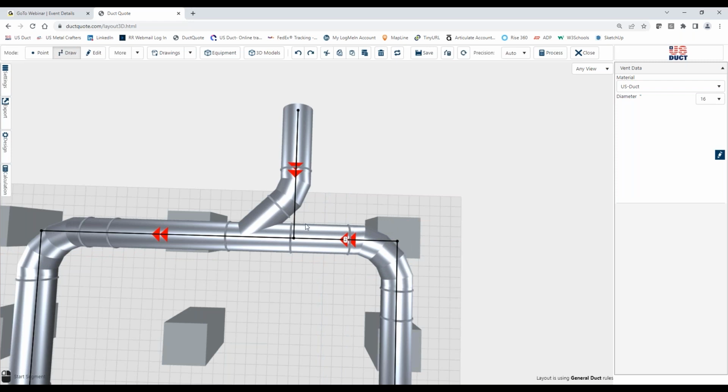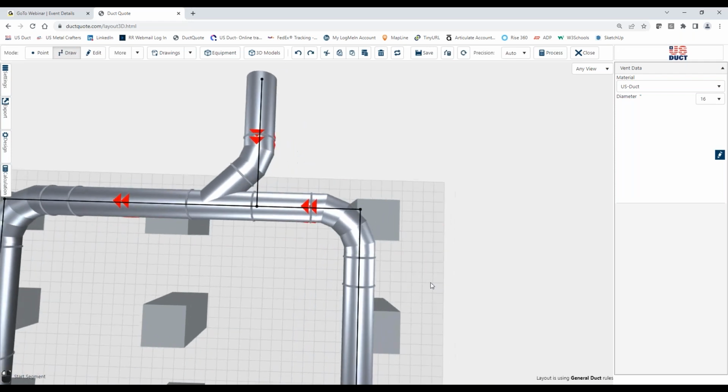So why is that different than something like this, which is a branch? Well, we've still got air coming here, and then we are shooting air into that, which disrupts not only this airstream, but also the main airstream as well, okay? So that is one of the big issues that cause that fan pressure to be higher. And again, we talked a little bit about the radius, and that is the rate of turn.